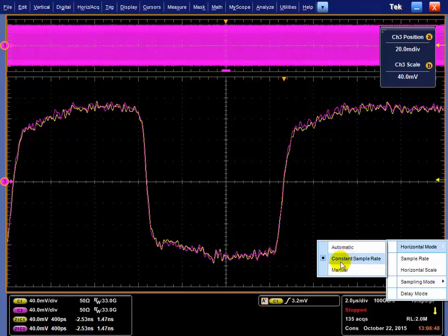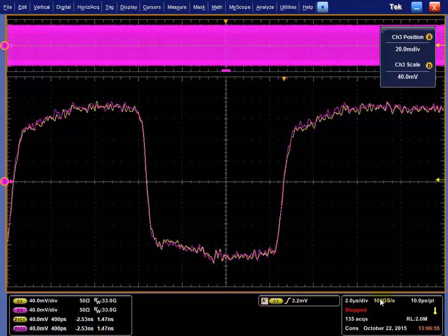That way you're in control, and you can also go to manual to get more details if you want. I typically pick constant. That means this 100 gigasamples is going to stay here while I'm using two channels, and I get the highest sampling fidelity that we've got. I'm going to grab a couple million points because I want to do some statistical analysis on this.